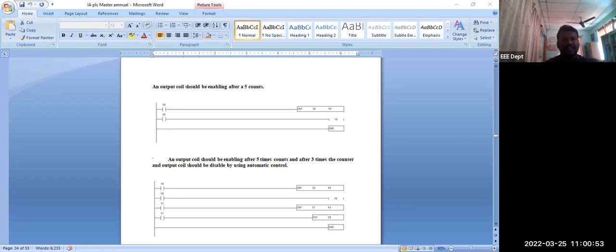Okay, so this is the counting. So you can set from 0 to whatever, 100 counts, whatever it may be, as you wish. Okay, so in this counting ladder diagram, you have to manually switch on the S0 every time, that each on off is nothing but one count.